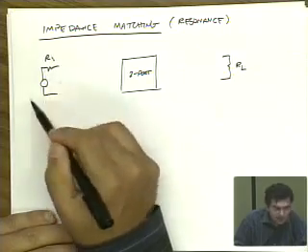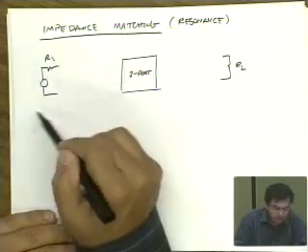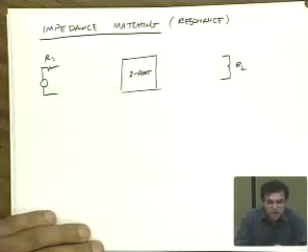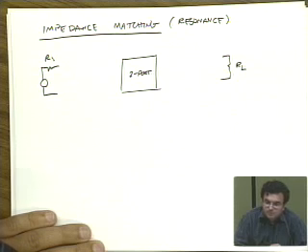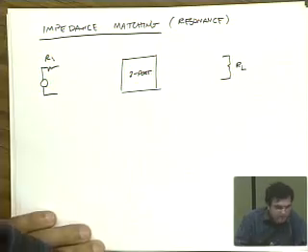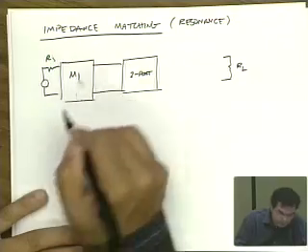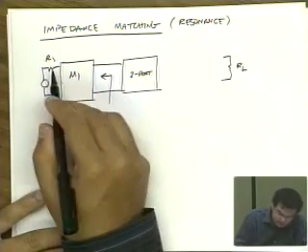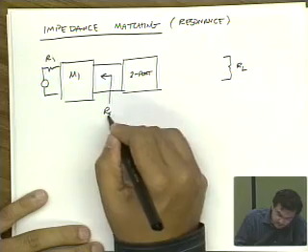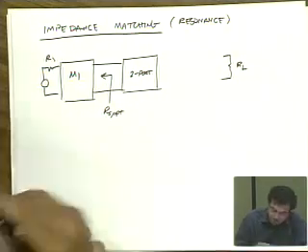For instance, this might be an antenna, and the person who designed the antenna says, well, when I design my antenna, the best I get is 300 ohms. So your source impedance has to be 300 ohms. And you say, well, actually, I want it 10 ohms. I kind of want to be driven by 10 ohms because that gives me better power gain. And the antenna designer says, tough. So what do you do? You actually design a matching network. We'll call this M1 that transforms RS into, let's say, RS opt. Or more generally, transforms ZS into ZS opt.